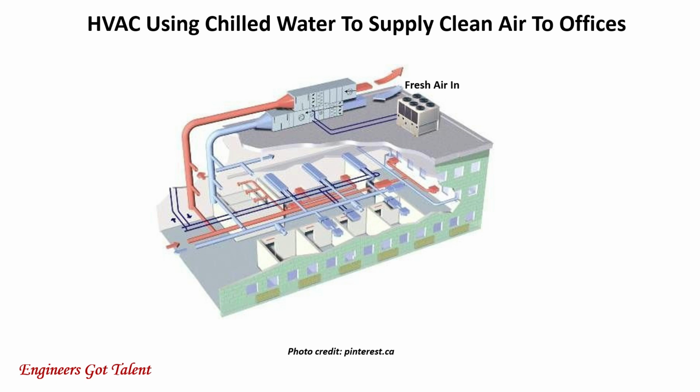So this is the outside air intake. The air goes to the AHU where it is filtered, purified, and cooled. Conditioned air then goes to the ductwork where it is distributed to different offices. The warm, dirty air from the offices is removed and goes into the return air ducting. The air then goes back to the AHU for ventilation outside of the building. A portion of the warm, dirty air is recirculated back to the AHU for filtration and reuse. The cooling tower cools the heat rejected by the condenser.